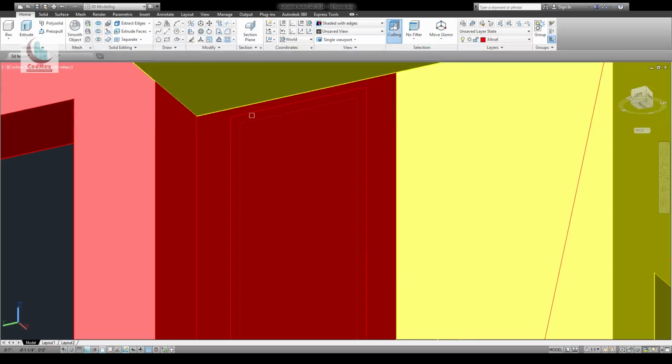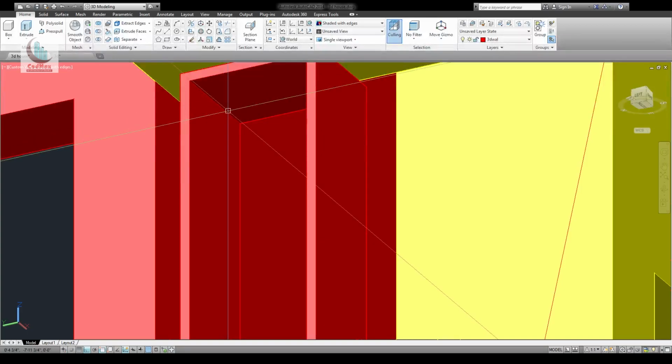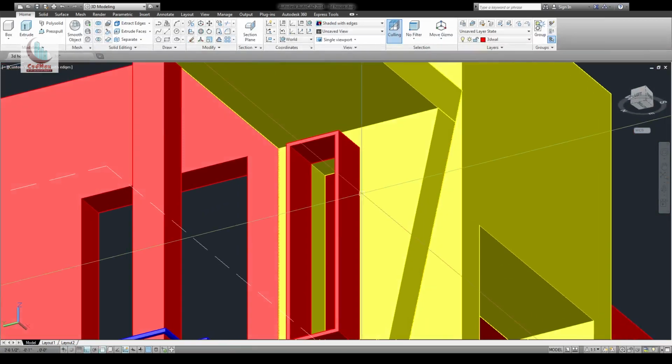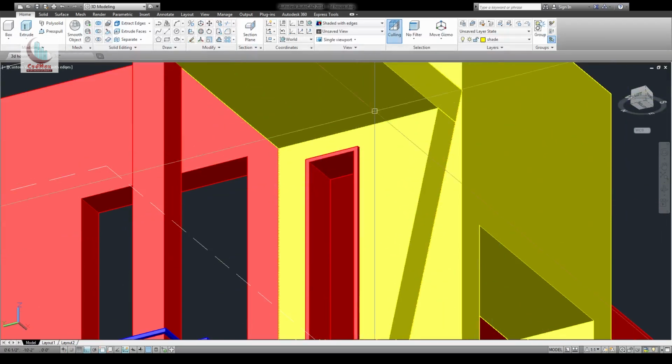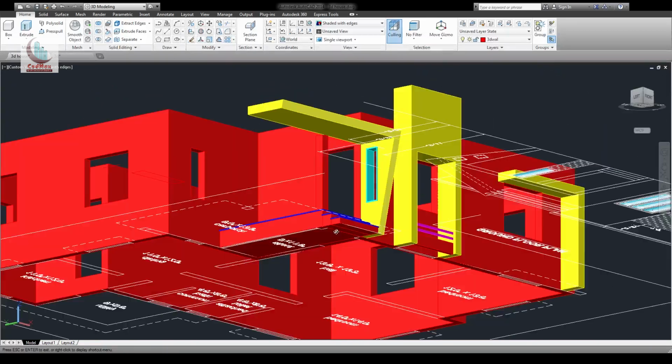Okay, now extrude this and this by 11 inch. Subtract that inside part. Okay, now you have to do oops command. There is a command called oops. It will bring back whatever you have erased. So you have to type OOPS. See, this has come back. Now move this back by say 10 inch. Okay, put it inside the layer called band.